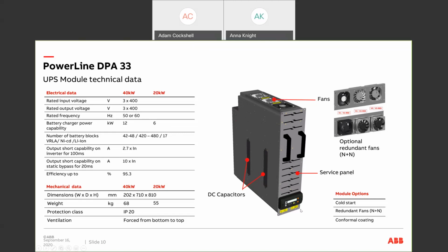Now, these are online hot swappable modules. Providing you have redundancy in your system, these can be changed online at any point in time for either maintenance or replacement purposes.